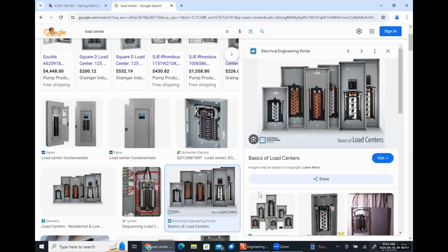So they have 120 for smaller loads and then 208 for their water heaters, ovens and all of that kind of stuff. So actually most appliances here in the United States have to be designed to work for both 240 and 208, so that you don't have to have special appliances for large scale apartment complexes. What does that mean realistically? Well, your oven's going to get slightly less current to it, which means it's going to take a little bit longer for it to heat up.